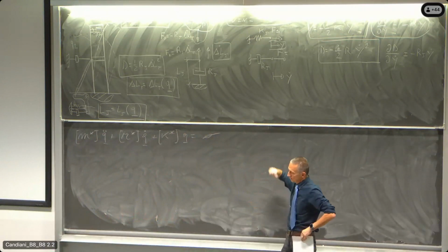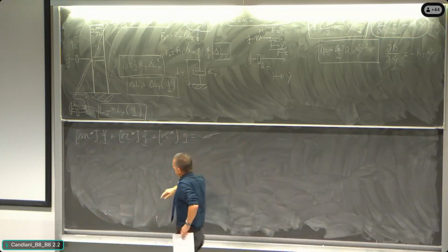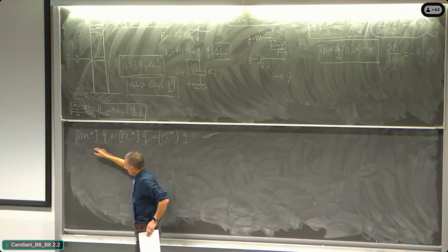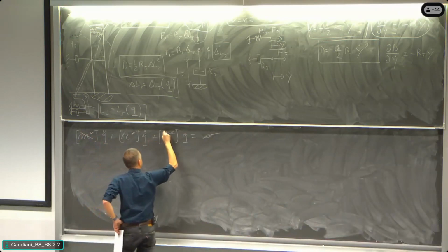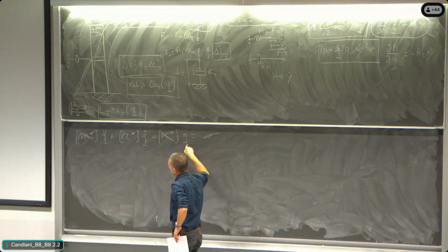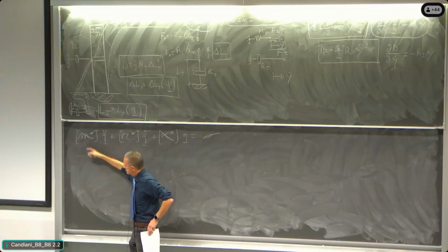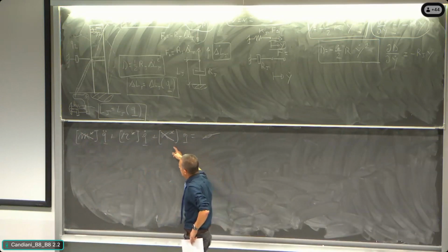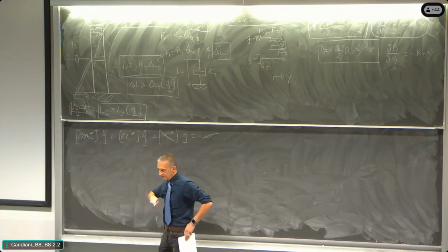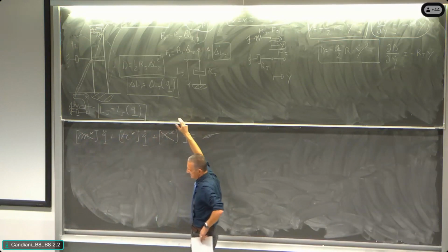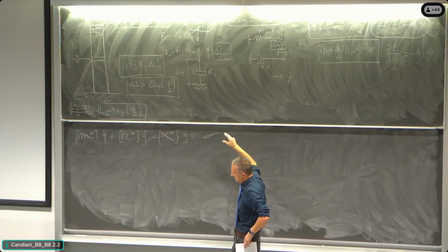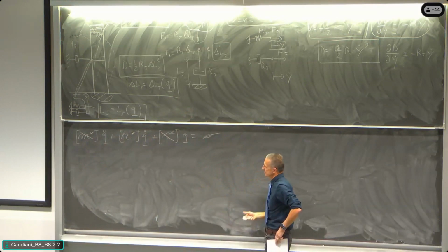So the final goal of everything is to write, finally, a problem in principal coordinates. And we already know that the problem in principal coordinates has a diagonal mass matrix and a diagonal stiffness matrix, and we don't know what happens about the damping, all right? So I am leaving here the question of the dissipative function. It is a detail, we are going to get to this detail, but first I want to focus on the final results, otherwise we are losing the goal of everything.